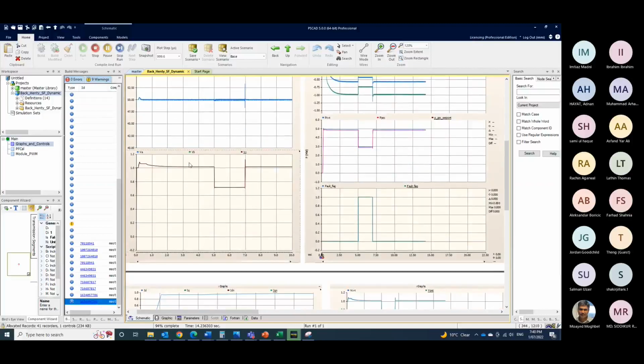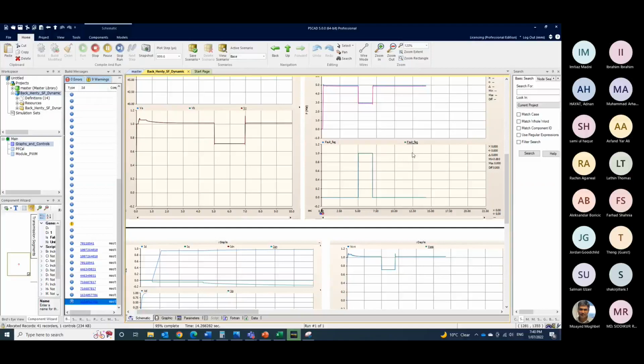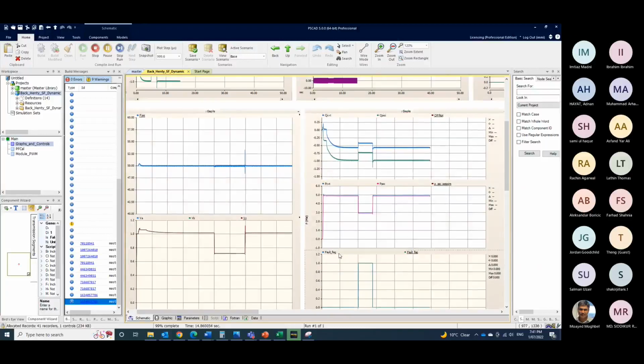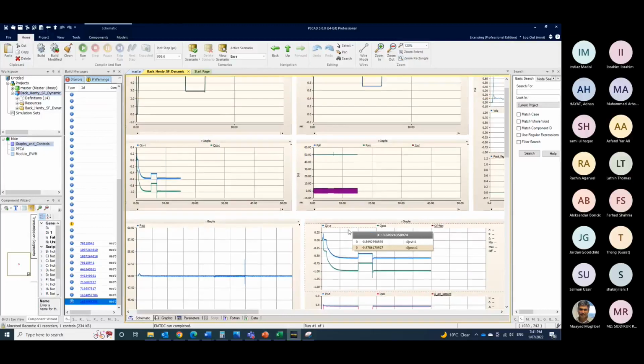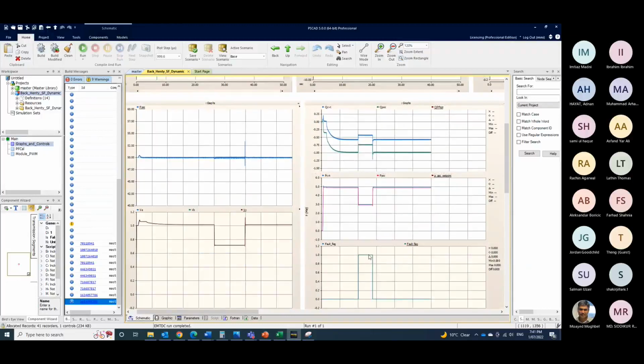Then we can capture line voltages and fault logs, so we can give you the fault code as well. The inverter manufacturer has these fault codes, and each fault code has a meaning. This one here is saying there's an under voltage. It is just a type of alarm flag. But when the fault is clear, this alarm also goes away.